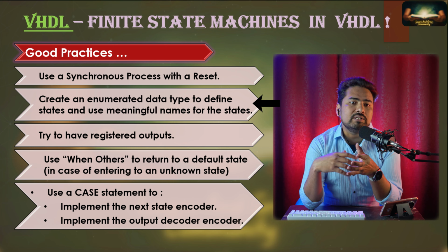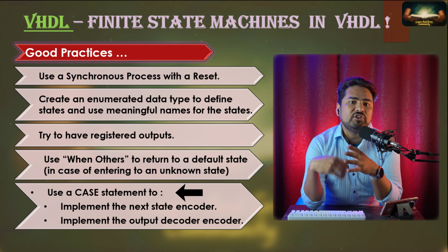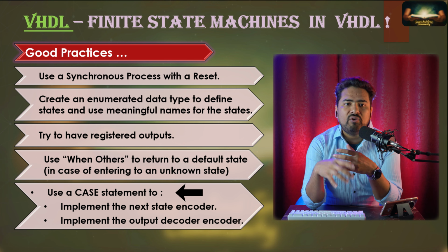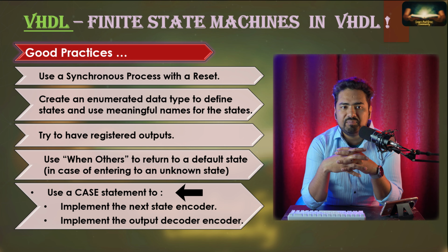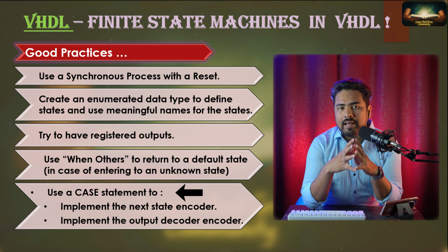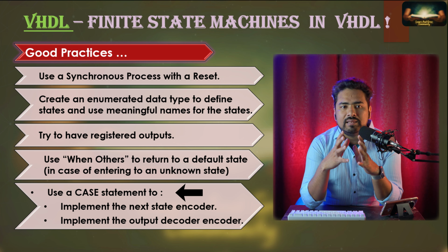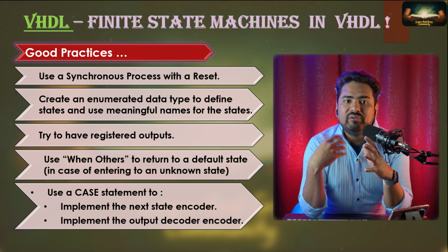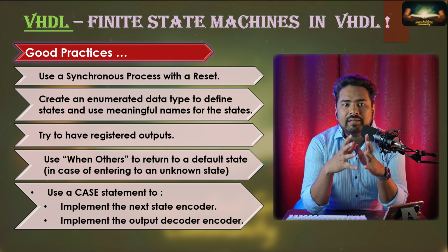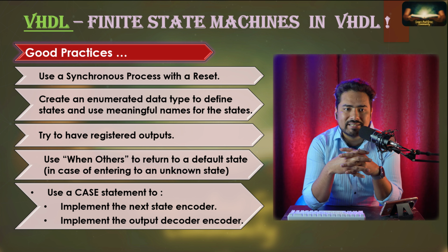Next, always use a case statement for any action against each state and also for defining your next state. So try to avoid using if-else statements, as they can create priority decoders in your hardware and this can create inefficiencies in your designs. Like we explained in the previous sessions, how they are inefficient and how they degrade your hardware performance.